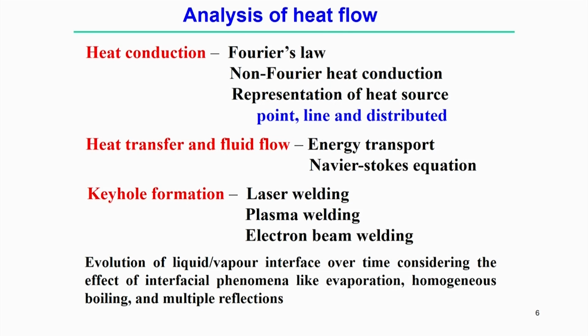Then another aspect, when we try to estimate the temperature distribution within the weld pool, is that sometimes in laser welding, and of course electron beam welding, and sometimes plasma welding, keyhole formation may happen. When there is a keyhole formation, that keyhole is a domain within the weld pool. Practically, when we use a very highly concentrated laser with very high power density, that actually creates the keyhole. In the keyhole formation there is an evolution of the liquid vapor interface.